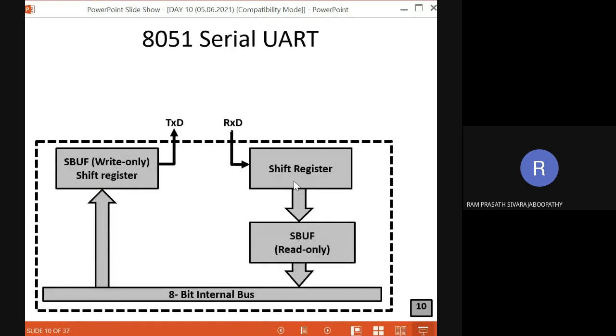On the transmission side, no worries, we are going to write, so transmission is under our control. But reception, I cannot tell when the other controller will send the data. So we have to give priority to reception rather than transmission. Transmission I can do at any time, but when we are receiving data, the controller has to skip whatever work it is doing and gather the data.